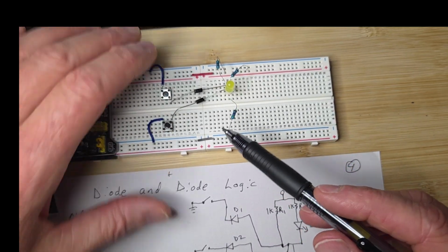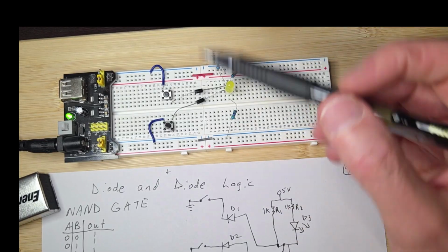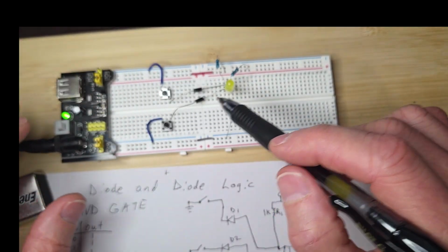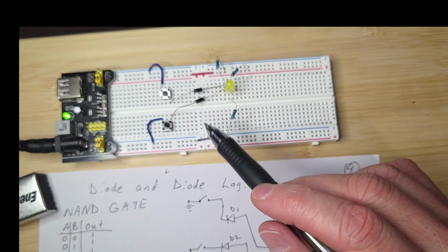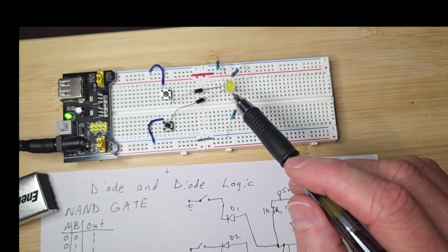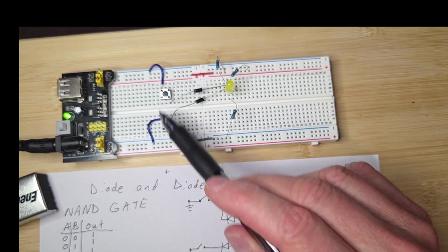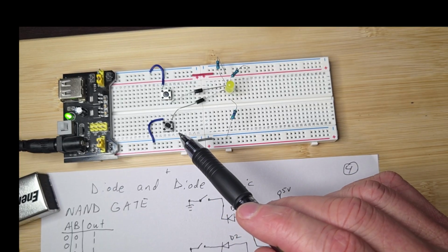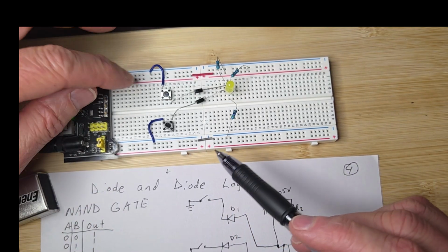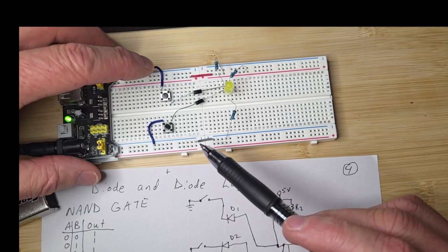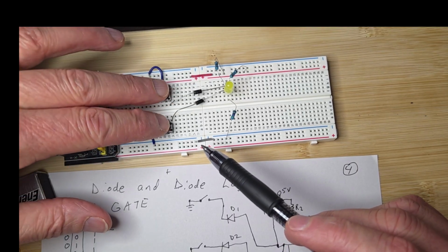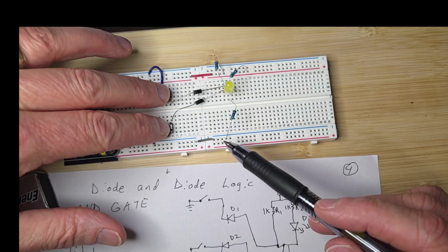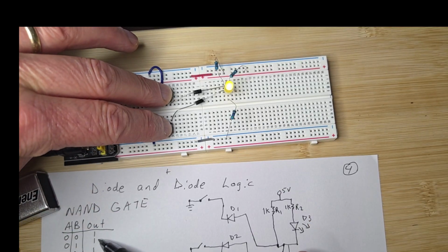What we're doing is, in our mind, considering that when these buttons aren't pushed, it's a high. Just think of it that if the button's not pushed, that's like having a 1 on there. So right now, A and B are 0, so you have to push them in to short them to ground. That means we get a 1, and you can see here on the truth table.